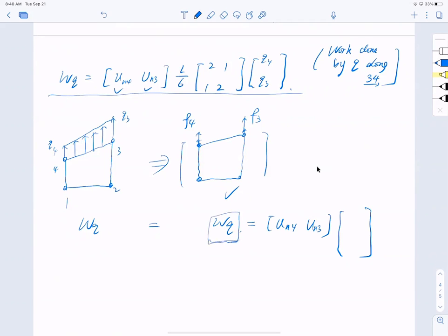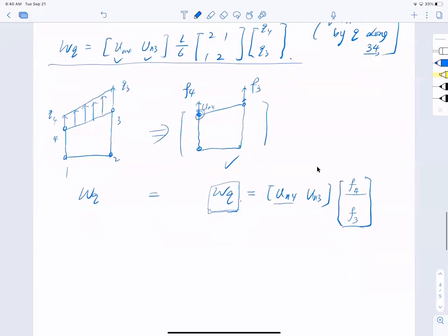Work done is force multiplied by distance, right? Yes. So I have a displacement here, UN4. So what do I have here? Force. F4, right? Because this one multiplied by this one gives you the work done by F4 at this node, right? So this one is what? F3. There you go. So on the right-hand side, it's extremely easy. I have 2 nodes. Each node will give me the work done, and I have displacements UN4, UN3. All I need to do is multiply F4 and F3.